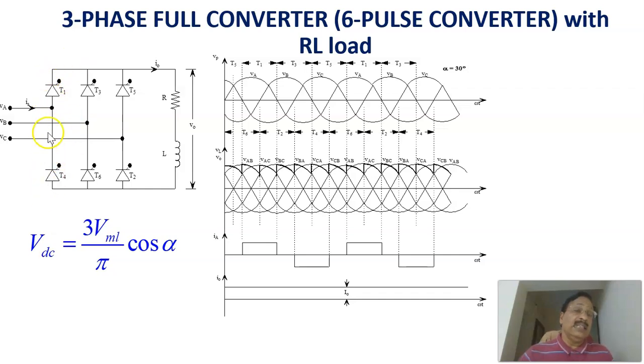This is the three-phase signal. In each leg there are two switches. Here I have shown them as silicon controlled rectifiers, SCRs. In each leg there are two switches and the three-phase voltage is coming. In a doubly fed induction generator, this comes from the rotor winding. Three variable voltage, variable frequency signals are converted into a unidirectional voltage.